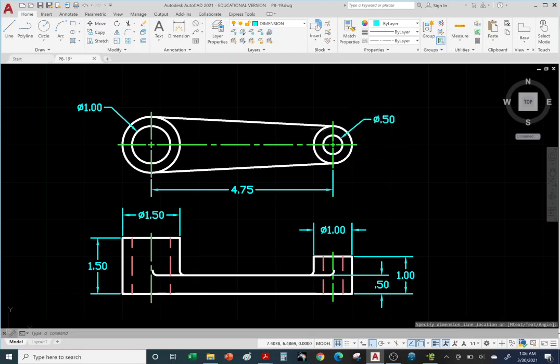and click. And if you're having trouble locating these diameter dimensions, you can simply turn off ortho. By turning off ortho, now you can use the grips. It's easier to locate your dimension by turning off ortho. So you can see I have freedom to locate it wherever I want. And once again, you want the leaders pointing downward. Let me hit escape and towards the center of the hole.